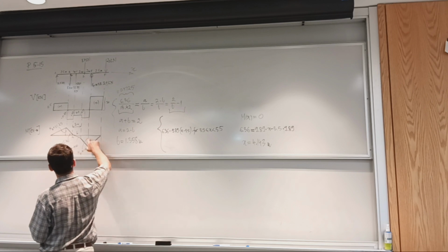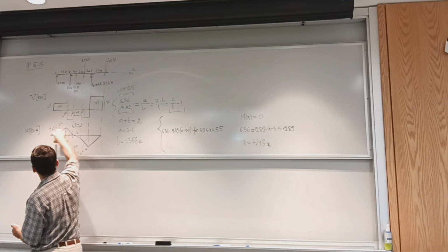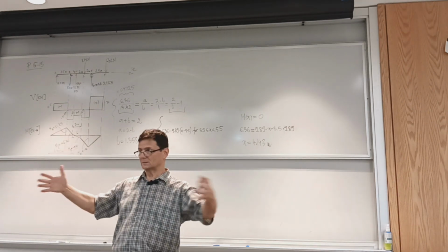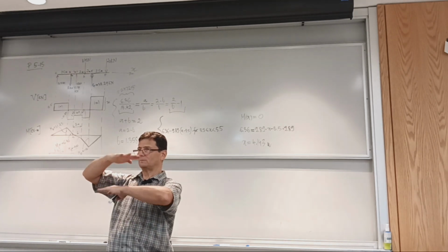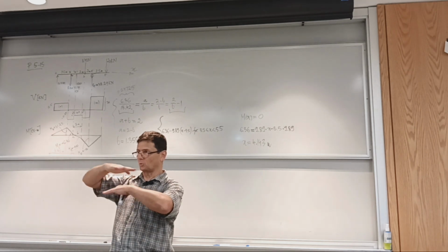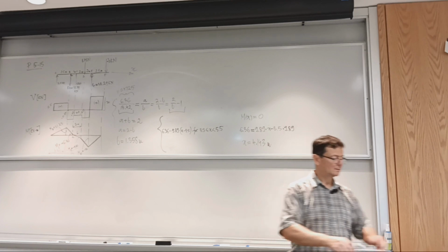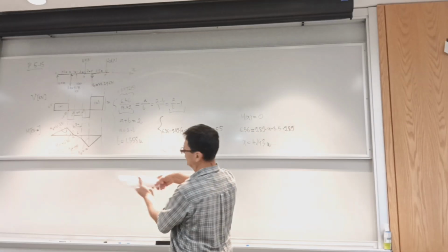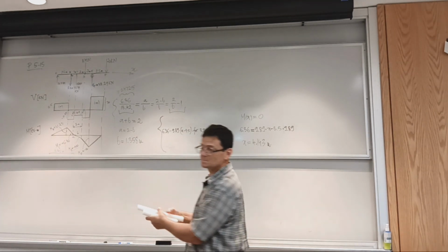Usually we're interested in the peak stress if the beam is constant, but the beam can have sections of different size, like a fabricated beam. You have a board, and then you add above and below, over a shorter section, 2 more boards to stiffen it. Does it make sense what I'm saying? So I can take these two and wrap them, and I get a beam that's supported at the ends, but reinforced in the middle.